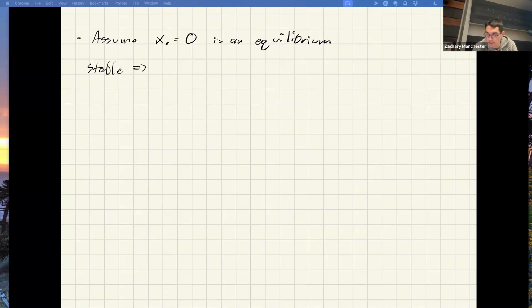So what's going on here, right? We can derive this. What we're really saying is that in the limit as k goes to infinity, I need A to the kth power times x naught to go to 0. Does that make sense? We're assuming our equilibrium is the origin here. Basically, k time steps of simulation looks like A to the kth power times x naught. If this thing's stable, it needs to go to the origin. That's what we're looking for as I make k go to infinity, for all time.